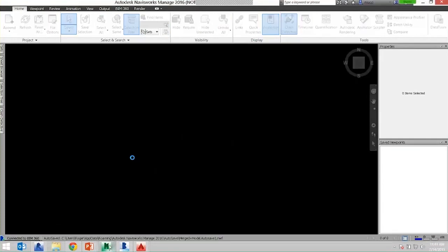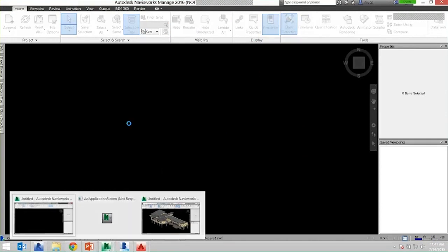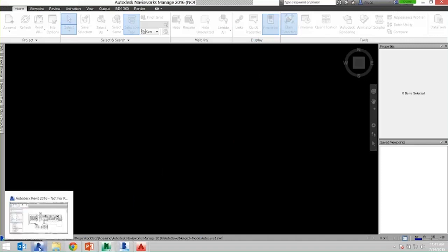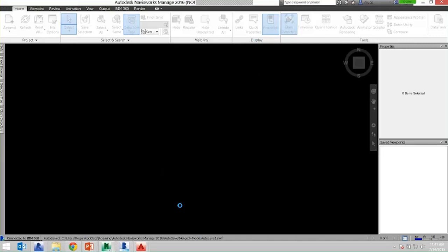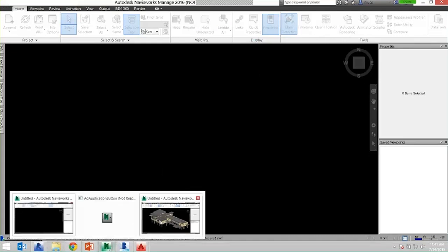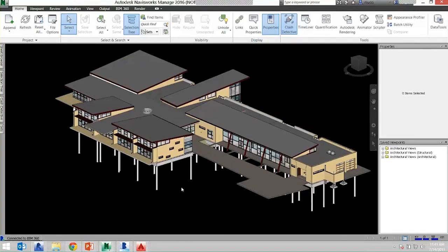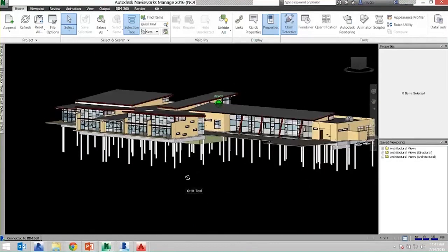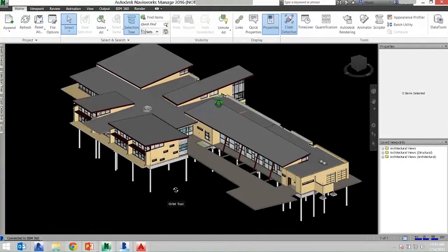This guy is still opening up Revit. But as Steve mentioned, instead of opening it up flat out like that and getting every single component, if I were to organize it in Revit prior and create that Navisworks view, it turns off categories. Maybe there are even worksets that are turned off, and it gets a view ready for the idea of collaboration and makes it a little bit more streamlined. I think that helps. If anybody has any other questions regarding that, feel free.